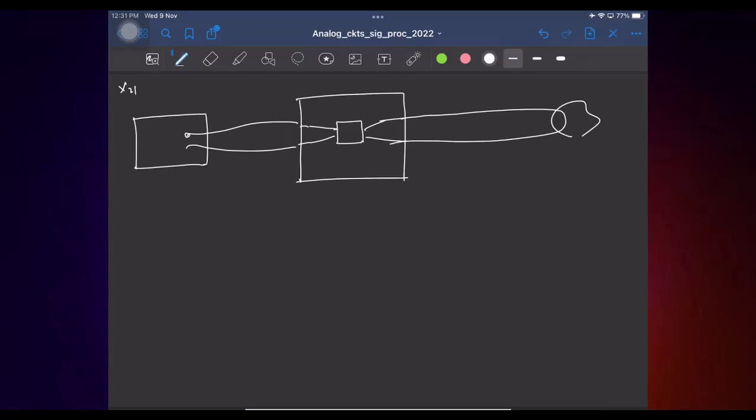Okay. So now you have learned, right? If you have long cables, you no longer can treat them as a simple short. So what is that? You have a transmission line, right? If I had to model this, this is the chip, the 2-port here, and then these cables are basically transmission lines.